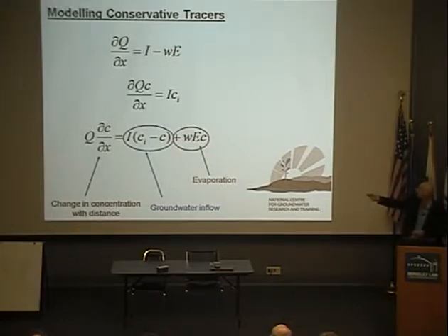And we can write a mass equation as well. The change in mass is just the inflow rate times the inflow concentration. Evaporation doesn't change the mass. And we can solve those simultaneously to get the change in concentration with distance as a function of two terms, a groundwater inflow term and evaporation term.